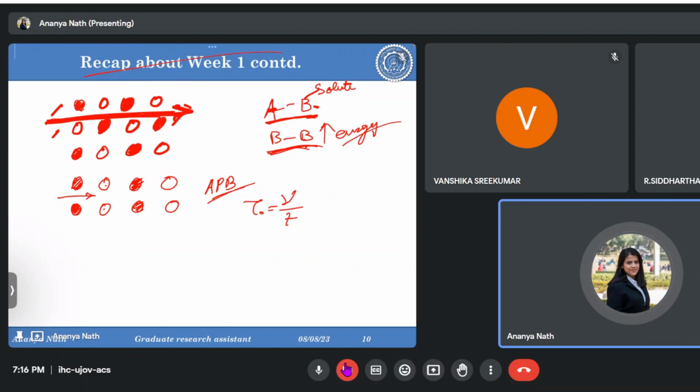And this rate of motion of diffusion, how they will move or jump into the nearby sites, how they move from one place to another just to catch up the dislocations, will depend upon the temperature and time as well. So it's a thermally activated phenomenon. This is why it's dependent upon the temperature that we are providing, or the stress also that we are providing externally.